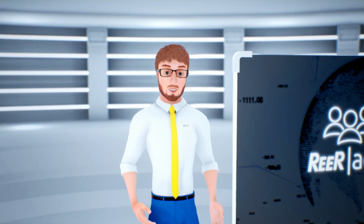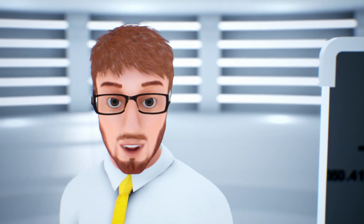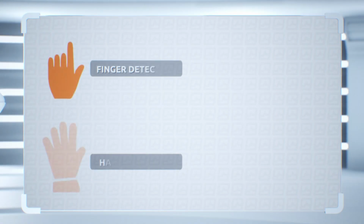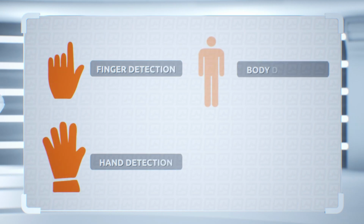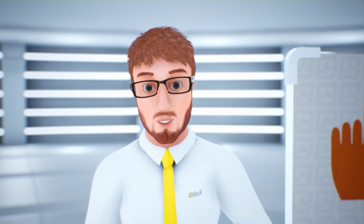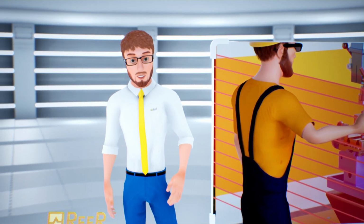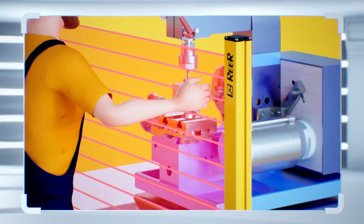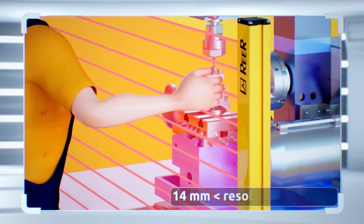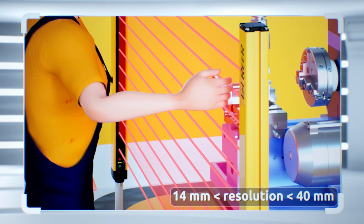In this episode, we will look at different light curtain resolutions, depending on the type of detection required by the application: finger, hand, and body detection or access control detection. When the operator is working closely to the dangerous point and, for example, a finger or hand detection is required, the resolution of the light curtain must be between 14 and 40 mm.